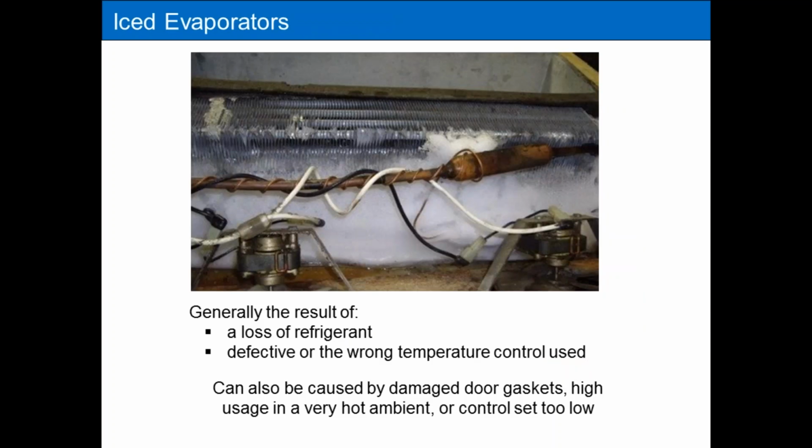All right, let's talk about iced evaporators. Pretty common problem. Iced evaporators could be caused by several different reasons. Loss of refrigerant can cause an evaporator to ice up. A defective temperature control can equally cause it to ice up. It could also be caused by high usage in high ambient, where the unit runs and never shuts off because they're